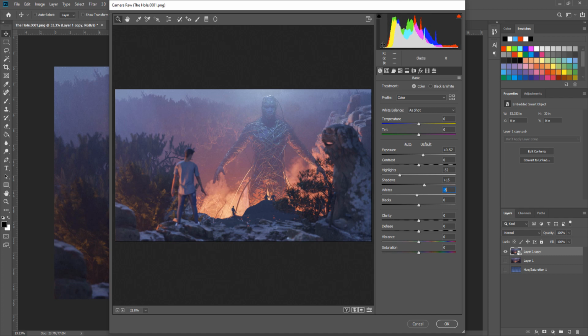With my histogram looking like this, I then just zero out. If I were to have a hill here on the left side, that would mean that my render is underexposed, and if my hill was right over there on the right and then nothing, then my render would have been too overexposed. I'll do the same for the black point. I'll just go to the left until this turns from black to anything else, until I see it turn red.